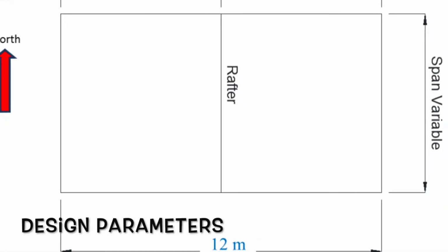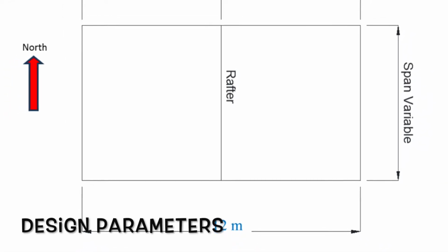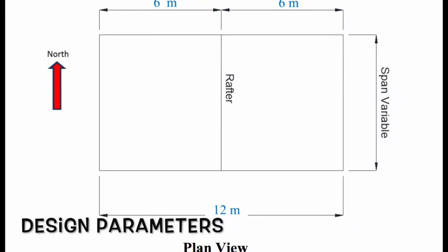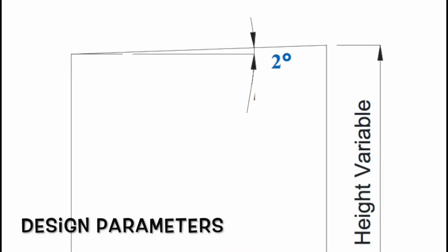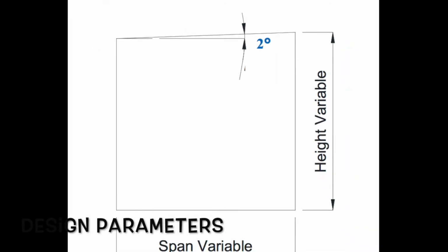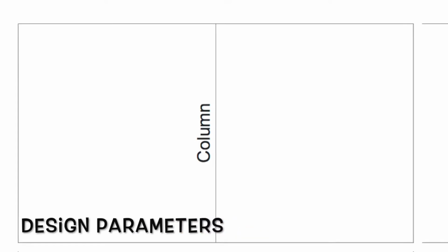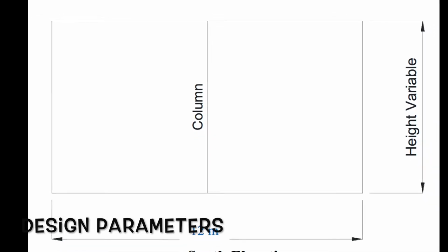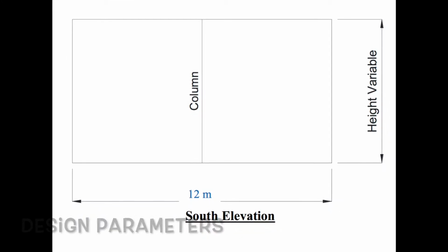For our group specifically, in designing our domestic shed, on top of the generic dimensions given, we had a span of 4 metres and height of 5.2 metres, being in wind region A and a wind terrain category of 3. We had to determine and design the loads applied on the building, purlins, girts, bracing, columns and rafters, using Lysaght products for the roof sheeting, purlins and girts, and universal beams for the columns and rafters. The connections are also to be pinned or a braced box structure.